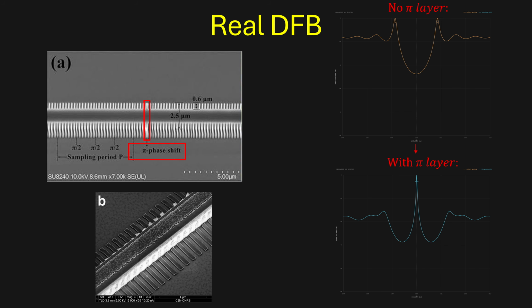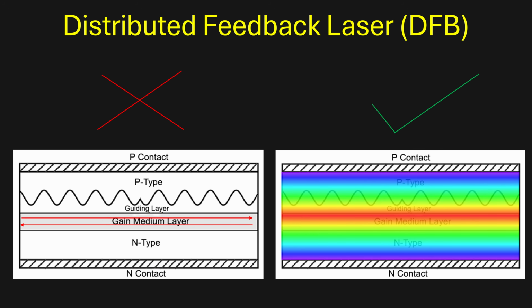In the center of the grating, there is usually a skipped transition that produces an extra quarter wavelength phase shift, which is included to prevent a coupling effect that produces dual lasing wavelengths. If you think of the light as rays, the Bragg grating is not very intuitive since there are no Bragg reflectors embedded within the quantum wells. So keep in mind that this grating is interacting with the entire electromagnetic field of light within the optical cavity, and it is able to cause reflection as if the grating existed at every vertical layer.